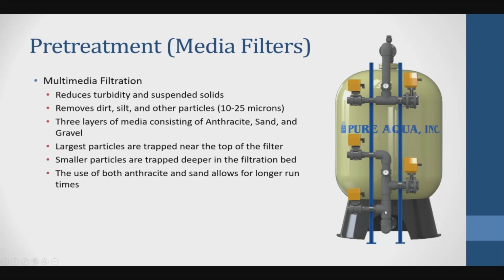Now the next cycle is the backwash. Backwash is required when the filter is running for hours and hours. It's going to block a lot of suspended solids. That means the differential pressure between the inlet and the outlet is going to start increasing. It's time to backwash the filter when the differential pressure reaches about 10 to 12 psi. 10 to 12 psi means if we measure the pressure that's feeding the filter and measure the pressure that's leaving the filter, if the difference is about 10 to 12 psi, it means it's time to do the backwash.